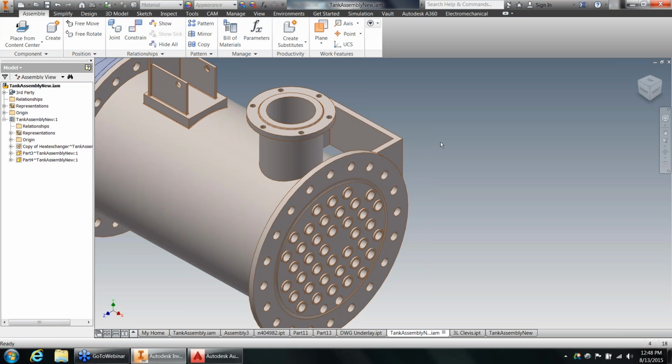So the way that these handle in the vault is it's all integrated. Basically, if I were to activate the vault on these designs, it would simply treat those objects as children. So it would bring those SolidWorks files into the vault and maintain the relationships as if it were a part within the assembly. With that, the check-in and out operations still take place. You would have to get the SolidWorks users the access to those files if you wanted to have them check in and out the documents, which does require some setup inside the space to do that, but otherwise is a pretty straightforward workflow.